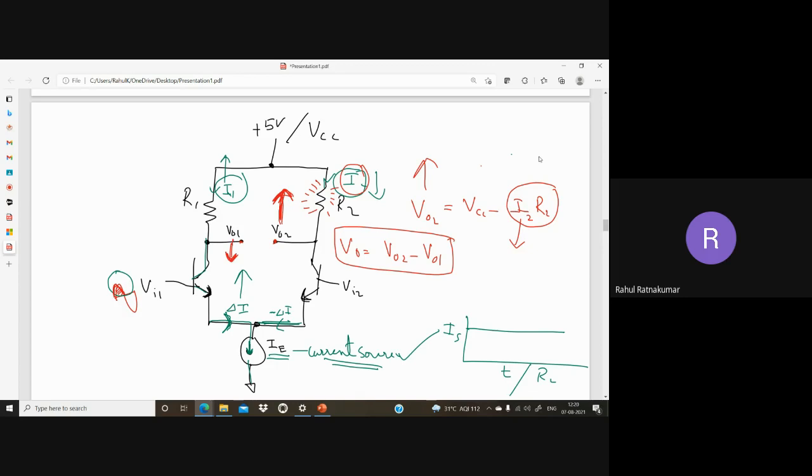Okay, this is not for exam purpose. I'm just giving it for your understanding. This is a differential operation. We have two different inputs, VI1 and VI2, and based on the input given to these individual inputs, my VO1 and VO2 are going to vary. If VI1 is increasing, VO1 is decreasing, but VO2 is increasing. If I take the output from VO2, it will be increasing. The same output from VO1 will be decreasing. So this is what is happening inside the op-amp.